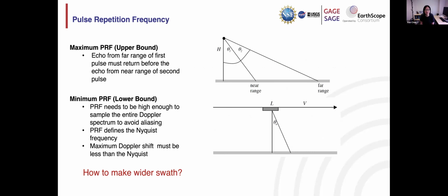And so here is another illustration for the Stripmap mode. The reason it is usually used for the earlier SAR missions is because there is a limitation on how wide the imaging swaths we can achieve. This essentially comes down to 2 requirements when we are designing an imaging radar system. The very first thing is how long we have to wait until we can send out another pulse, right? Ideally, when we are at a position, we would like to send out a pulse and collect data from the near range direction to the far range direction.